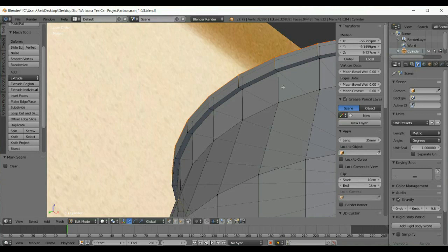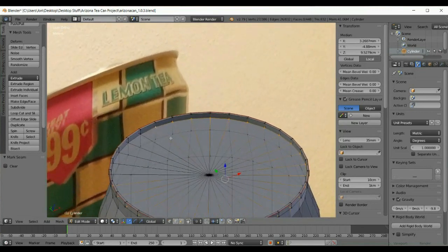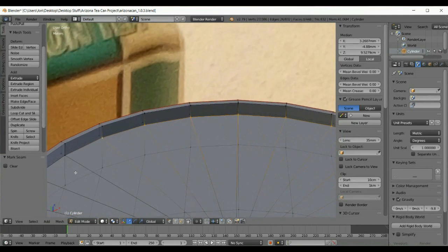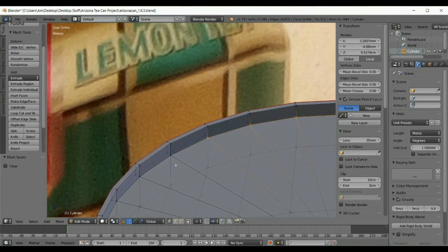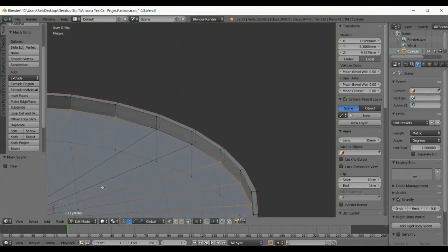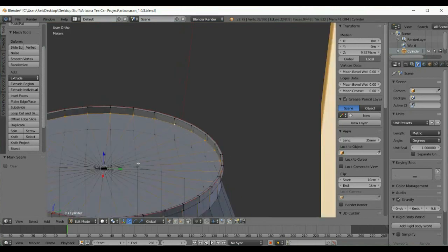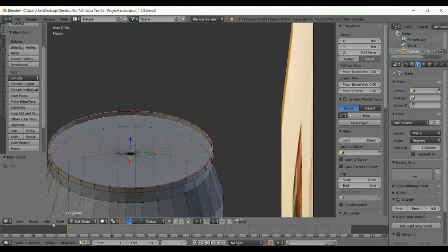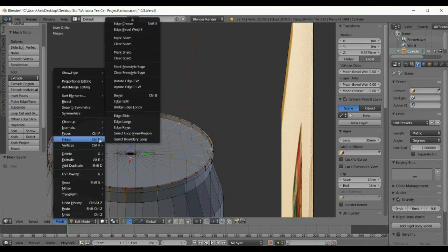All right, so I am going to mark this seam now. So right-click, shift right-click, shift right-click, and so on. And I'll move around the rim, and we'll jump ahead in the video. Of course, in this situation, I'm getting close to finished here, I should add that because this seam is shared with the top, what that means is, in part, you can select from behind, like this. So from a view standpoint, it's a little bit easier. See, if I just swing over here, I select these, and then we got the seam. Now, another thing, well, first of all, we will go Mesh, Edges, Mark Seam, and we'll have to finish in the next video.